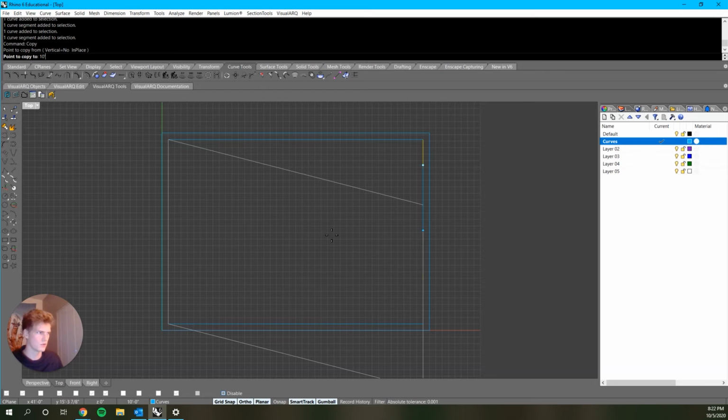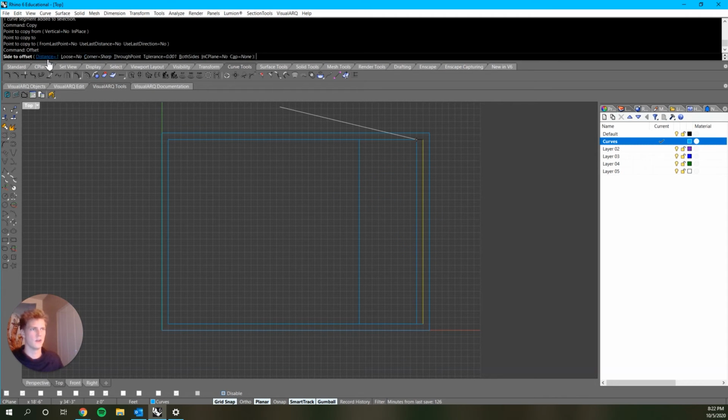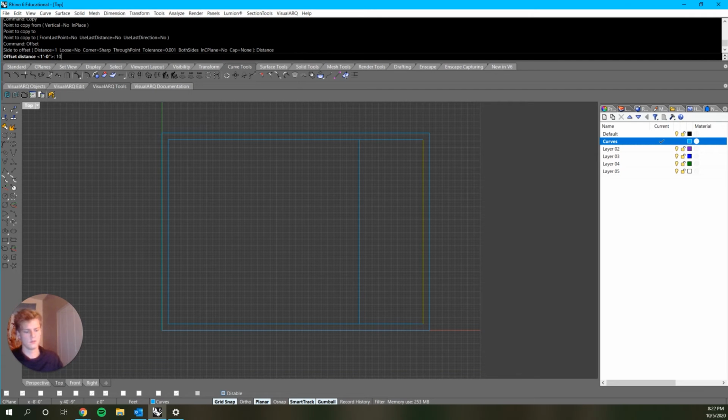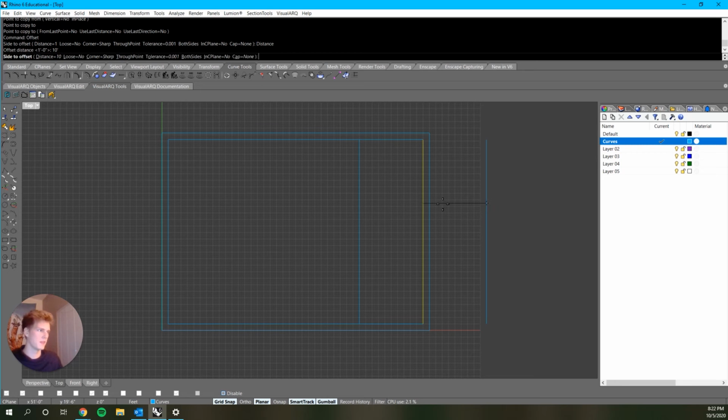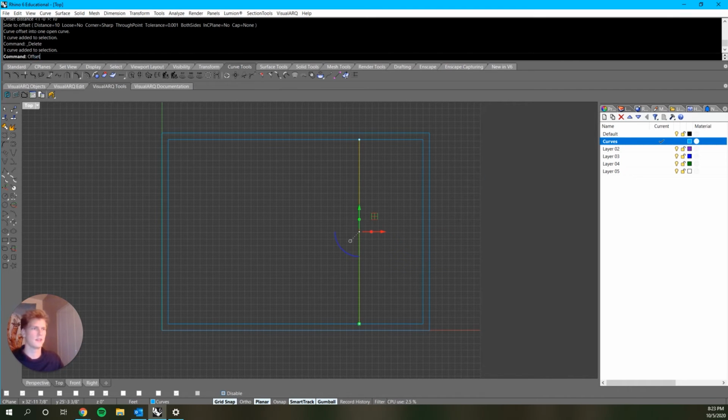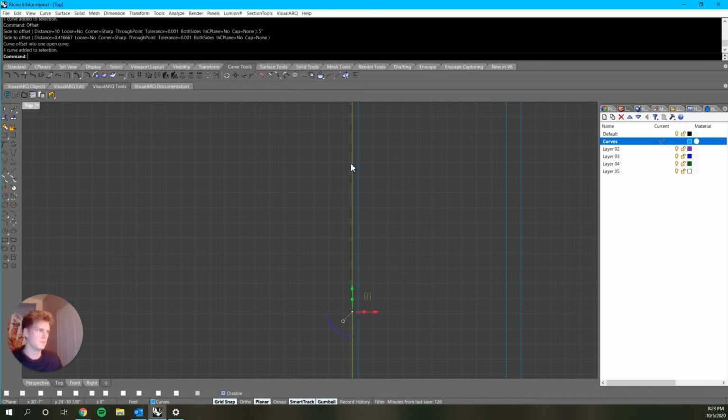And if you hold Shift, of course, like we did with the polyline, it'll snap you to the orthogonal projection from that line, right? Alternatively, you could run another offset, and under distance, you could click up here, click distance, change that from 1 foot to 10 feet, and that will let you do a similar command. You can start to see that there's a lot of different ways to do different functions in Rhino. From there, you could take this one, offset that, and maybe you want only a 5-inch thick wall, right? So you could say, yep, 5 inches there, done.